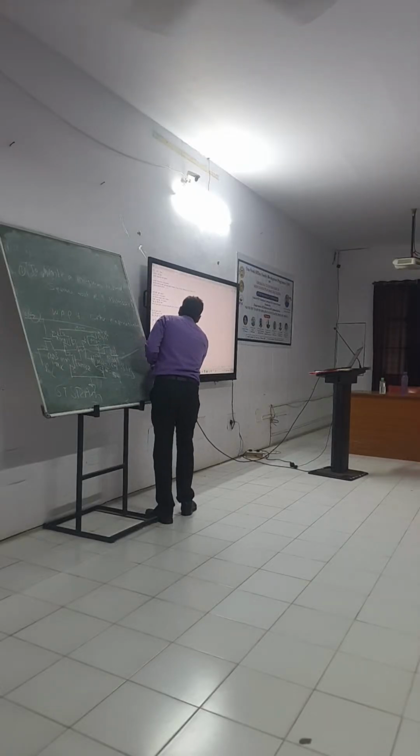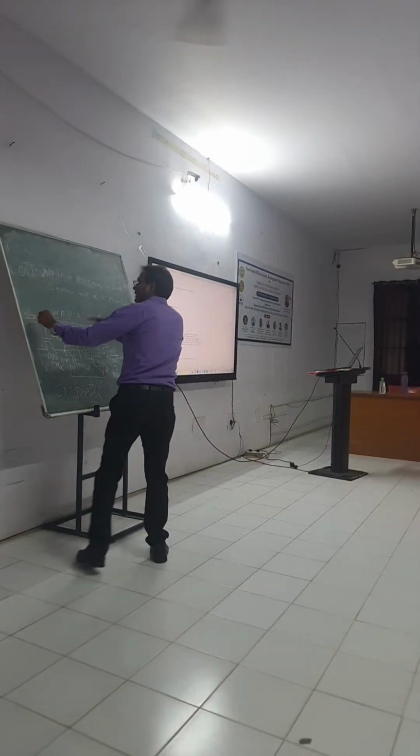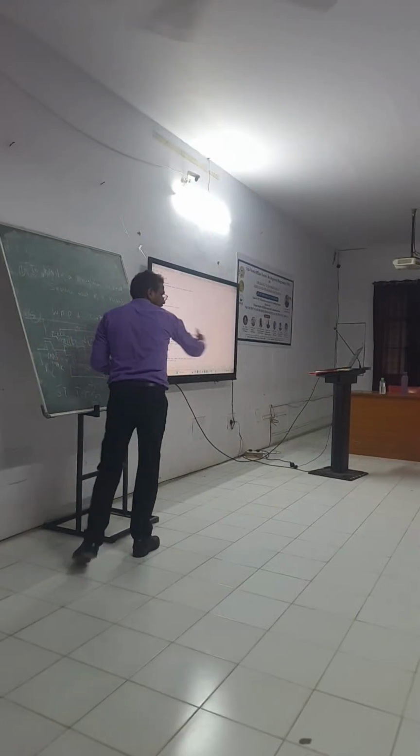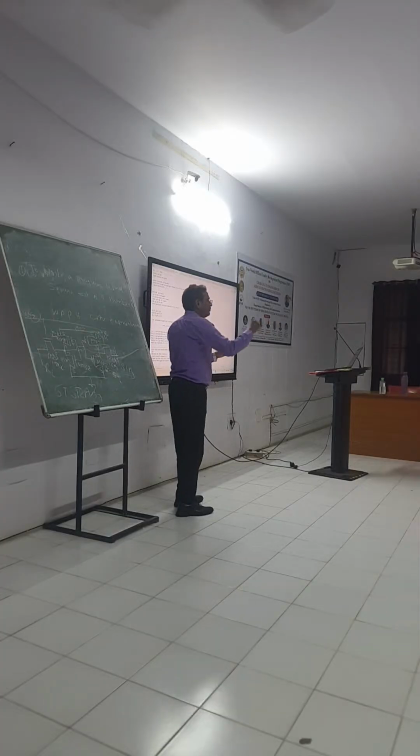So what do we have to do? We have to trigger VWL. Why V? It is voltage type. Where are we applying it? At WL. So at WL we are applying a rising pulse. When this voltage is above the threshold voltage, this one and this one will be on. Get it? So for that we have to apply triggering. Its value should start from almost 0, and it will rise, first rise.